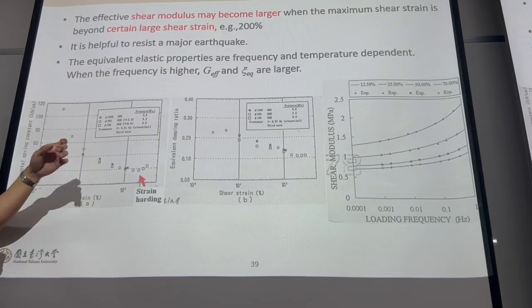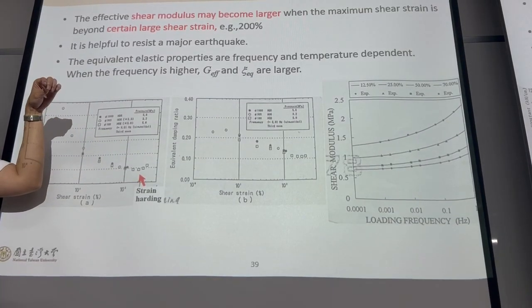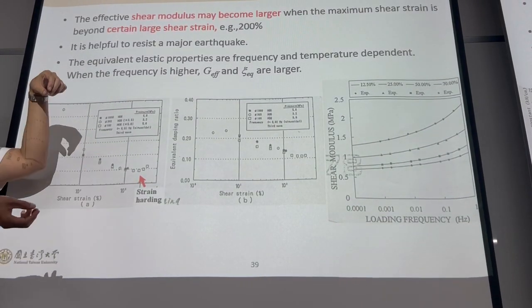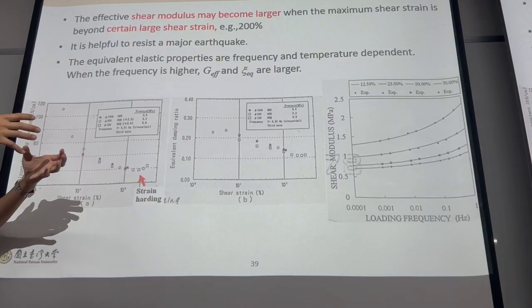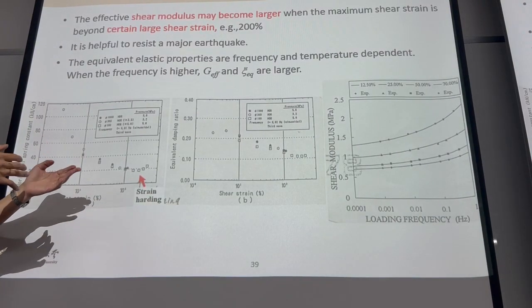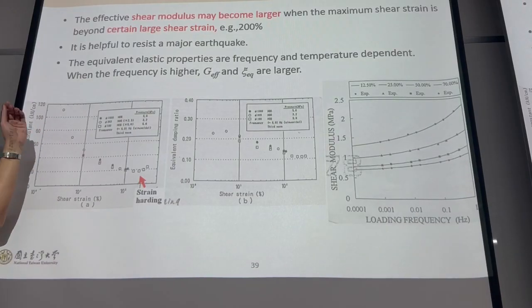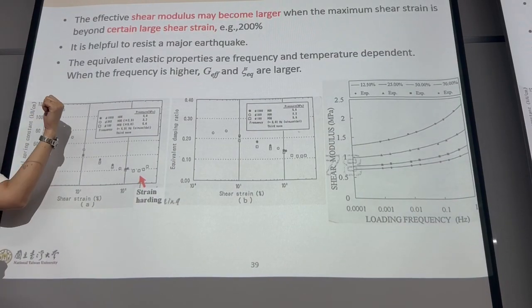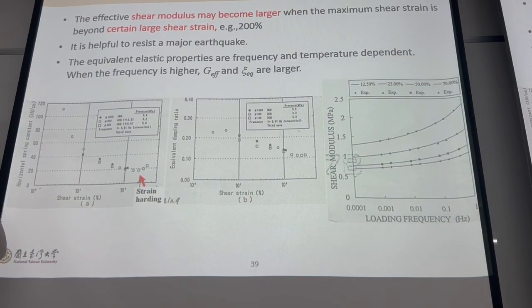But still, it's a very good material because you don't need to consider how to combine the lead core with that rubber again. So you use uniform material and you still do the metal shim, and you can reach what you want without that lead core.